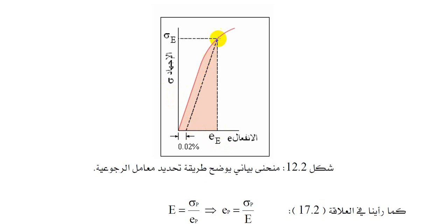This is the oblique line, or the inclined line, which intersects with the stress-strain curve at a certain point, and will be mapped to the vertical axis at which the stress is plotted, to extract the proof stress value from the corresponding stress-strain curve point.